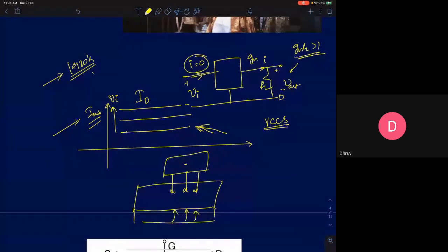If I apply a positive charge here, it's going to draw electrons closer to the surface. Then I'll apply a voltage between these two terminals of the semiconductor, and I'll have a current generated between these two terminals, and the value of the current will depend upon the voltage that is applied or the field that is applied.